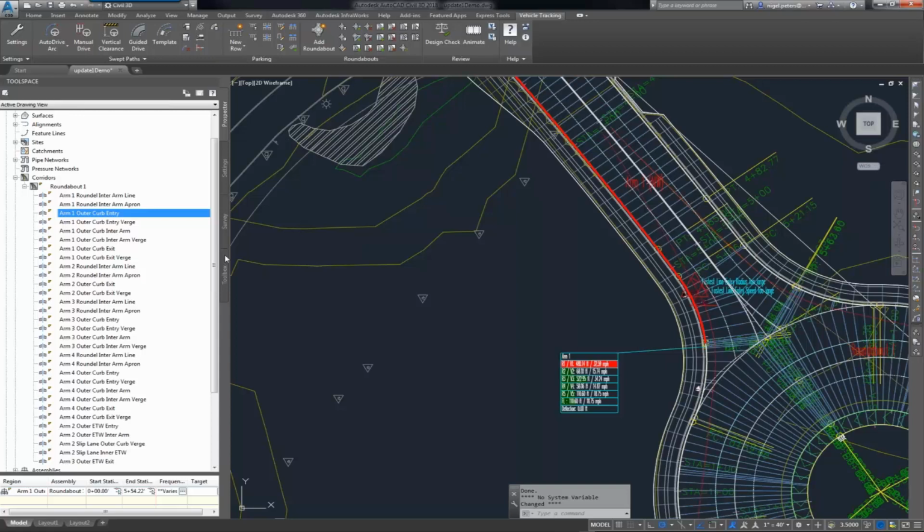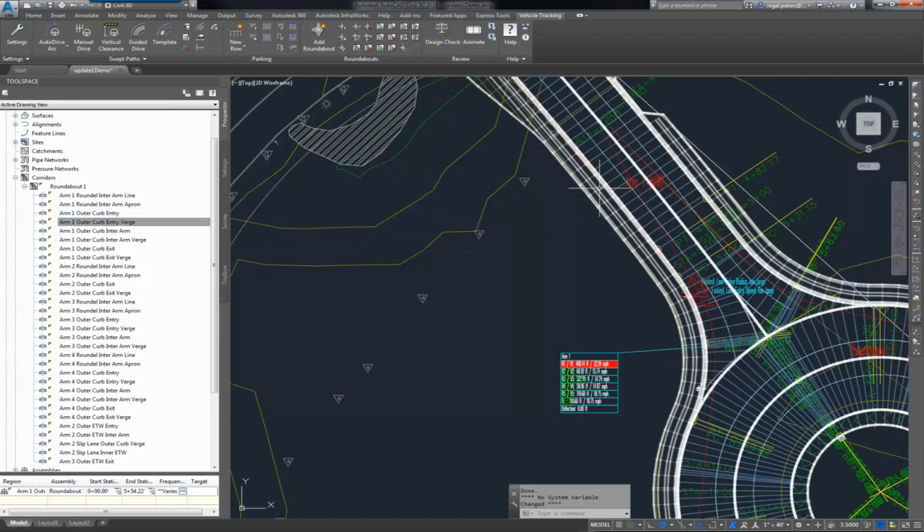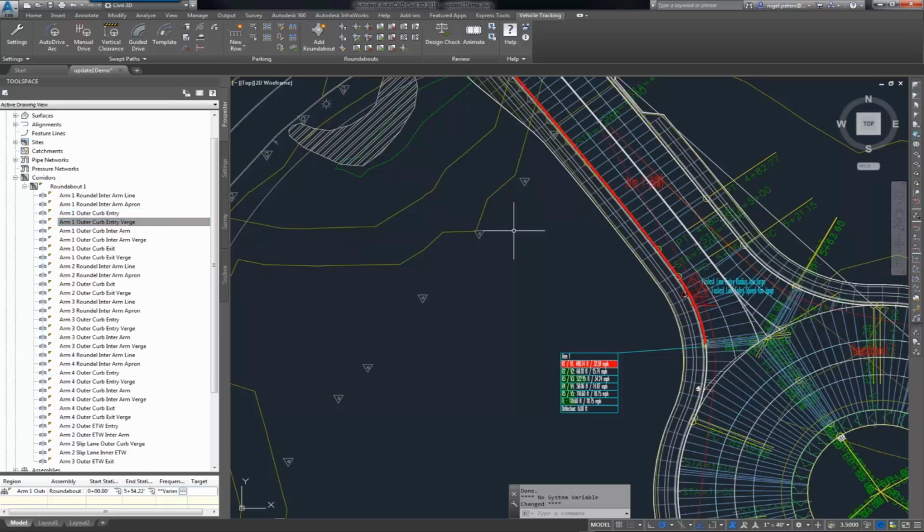The cross-fall and cross-slope, our alignments come with calculated profiles and elevations. We're not using cross-fall equations, so we are actually targeting the profiles elevation. We also cap the verge or cut and fill or curb line is built outwards, again per region, per arm, and we split the entry and exit separately.